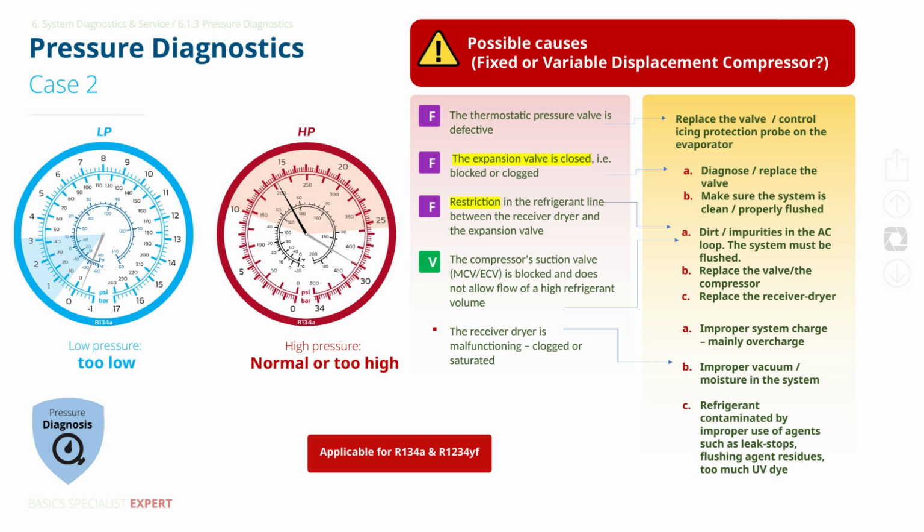If the evaporator or expansion valve freezes, the refrigerant can't properly change from liquid to gas. That sends liquid refrigerant back to the compressor's suction side, something that can quickly damage or destroy the compressor.